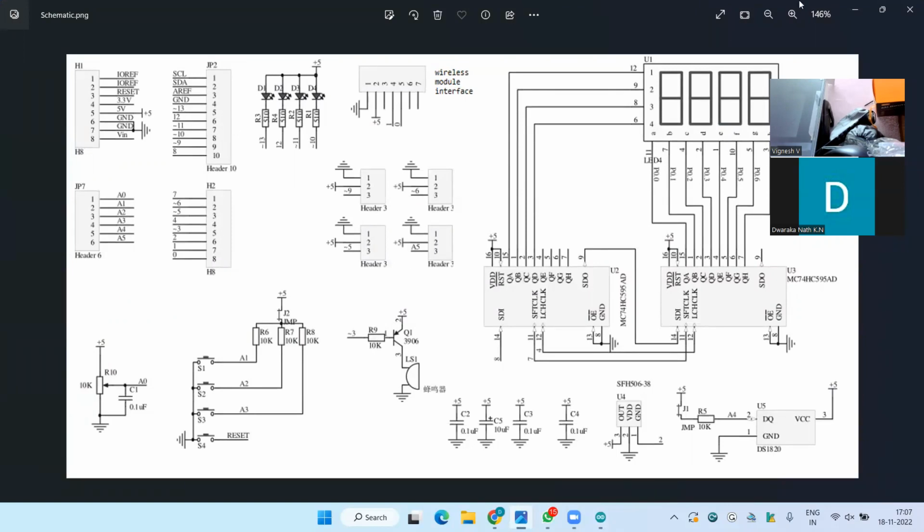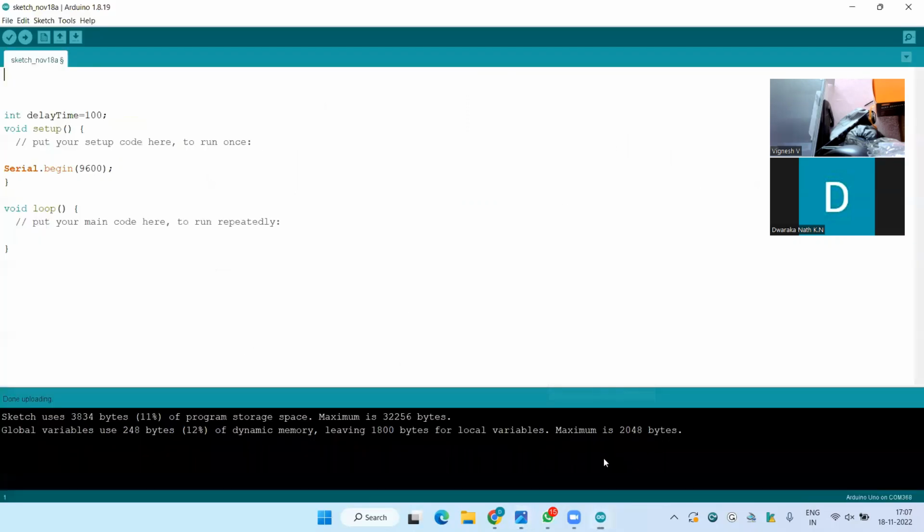So we will activate the buzzer now. Now coming to the buzzer, int buzzer is equal to pin 3. As per the data sheet, the buzzer is connected to pin 3. Now we need to tell pinMode that our buzzer is at pin 3. So in void setup, we need to tell pinMode buzzer is output.